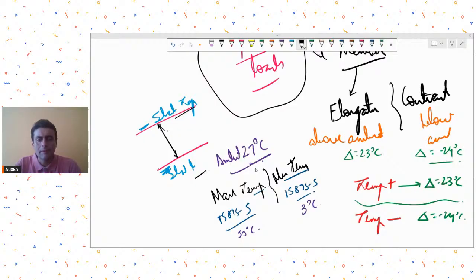He had asked something about the continuity of purlins if we are providing slotted holes. I think that was his question, that if we are providing slotted holes at the purlin to purlin overlap, how do we consider it to be a continuous purlin?